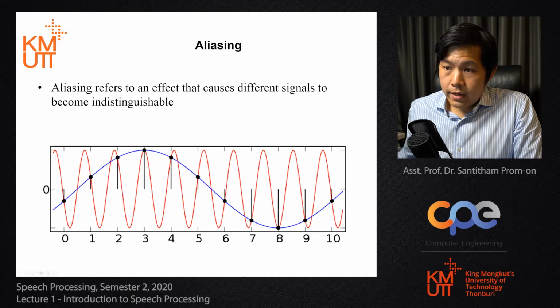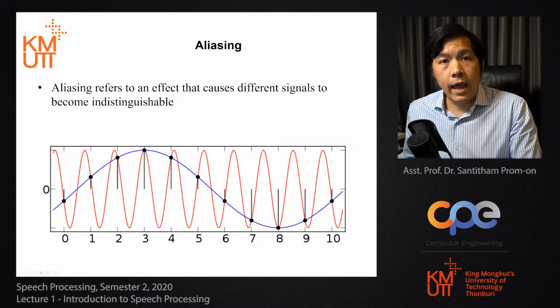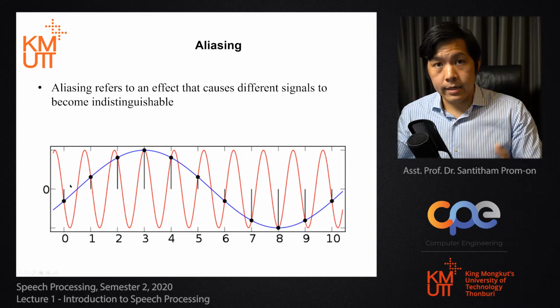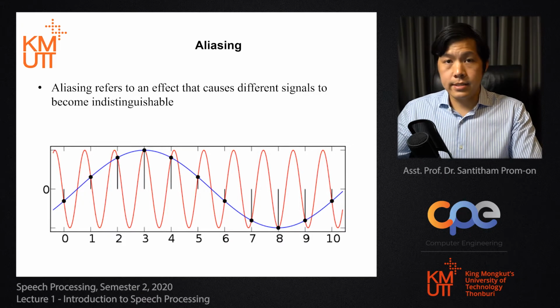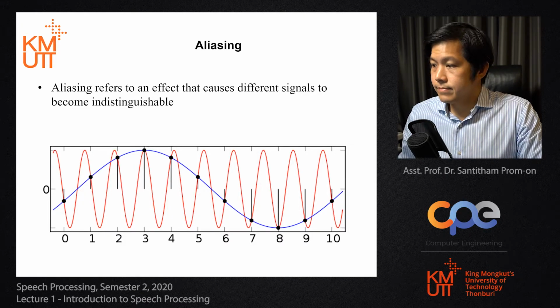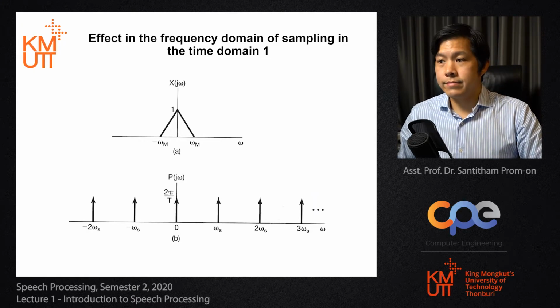You can see that the data we have there, the red lines have high frequency, but if we sample it with lower frequency here, it creates a type of blue line here that is not the actual data, right? It is distorted from the actual data. This is the aliasing effect, right? How does it work in aliasing effect?